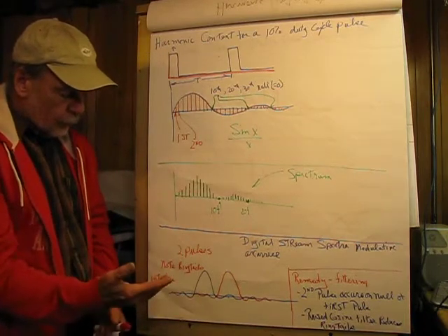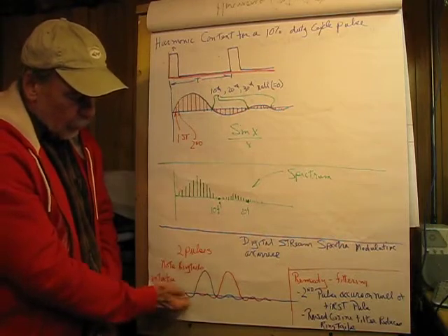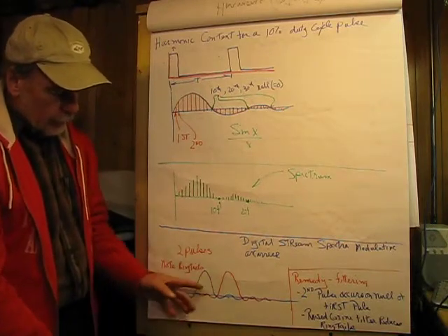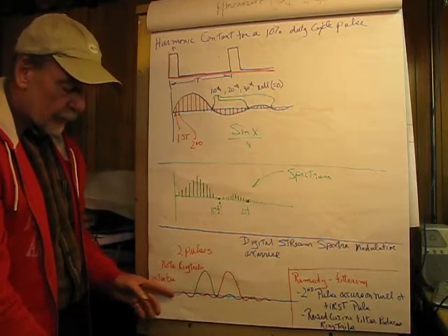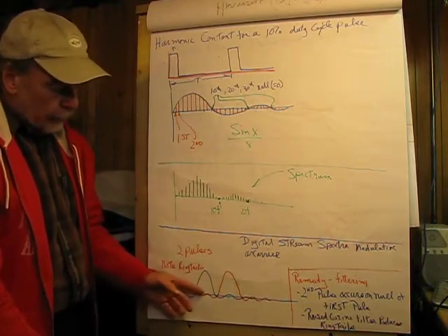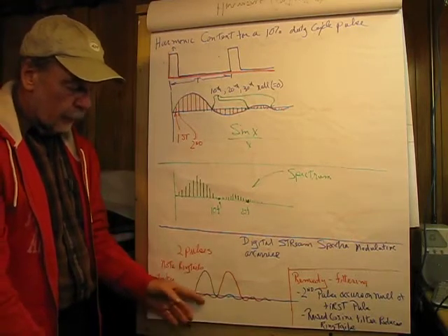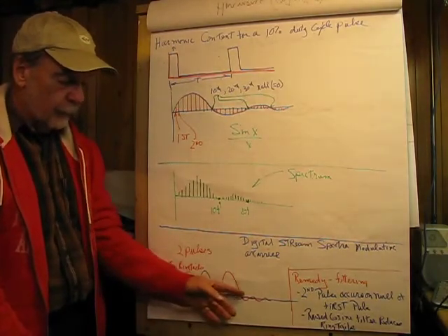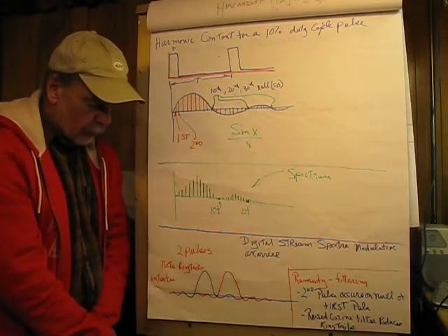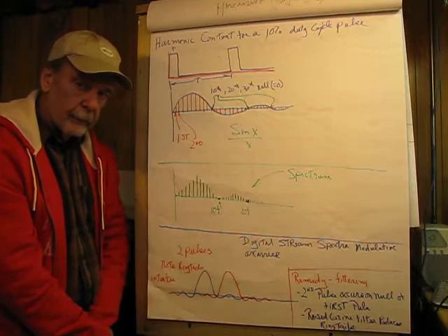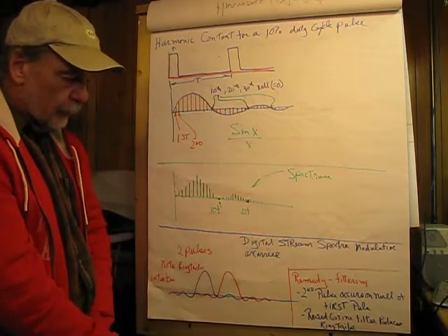So if we consider two pulses here, one being in blue and the other one being in red, you can clearly see that the ringtails on the blue guy and the tails actually preceding it will sort of overlie some of the time for the red pulse, and likewise the red guy will be interfering with what the blue pulse is, and also with what follows the red. So this is a good example of inter-symbol interference.